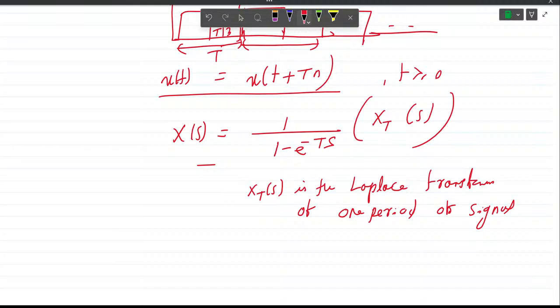Like you have an operational amplifier, you have a capacitor, and you have a switch. When you close the switch, the capacitor will start charging. At a certain point of time the operational amplifier output will go to some set value, and that will trigger a digital circuit, and that will trigger the other components in cascade.